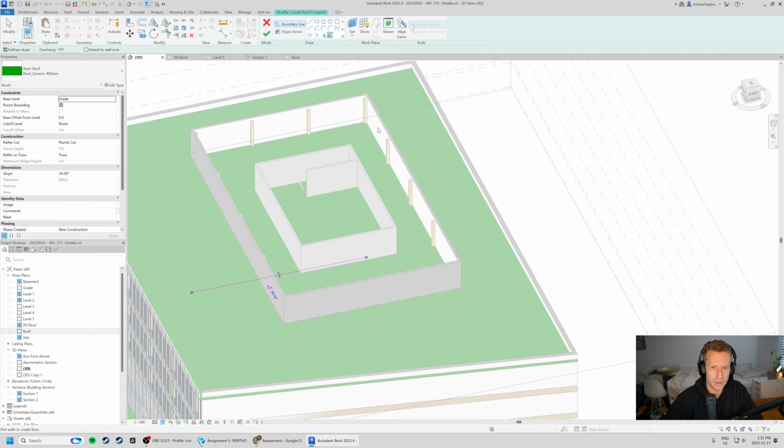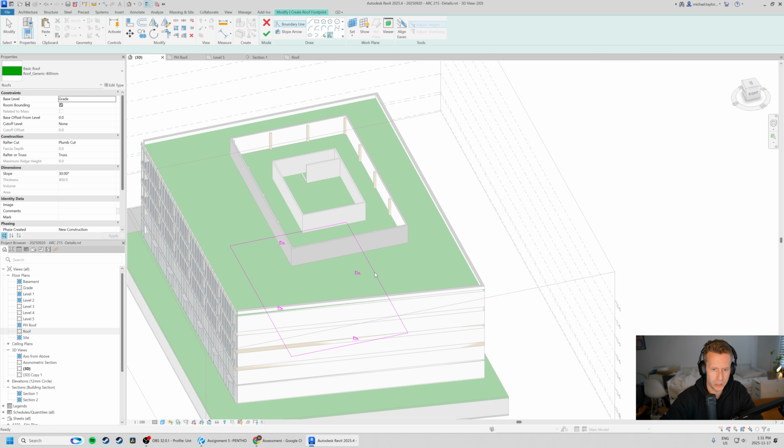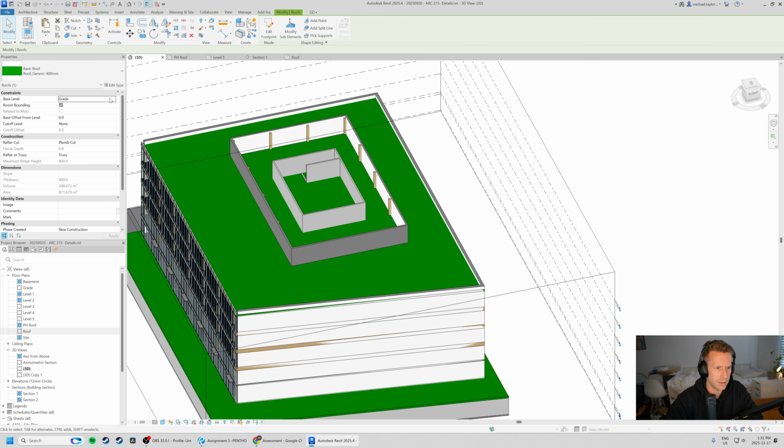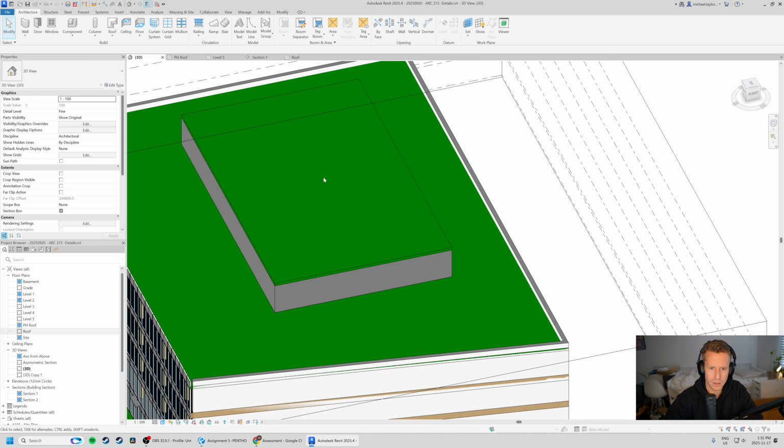I'm going to go ahead and create a little roof. Make sure you don't want to define any slopes up here. And now, check mark, and it's at grade. Make sure you put it at the roof level. In fact, let's put it at the penthouse roof level. Ta-da!